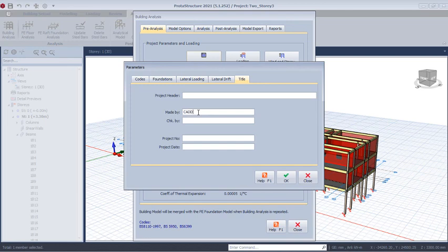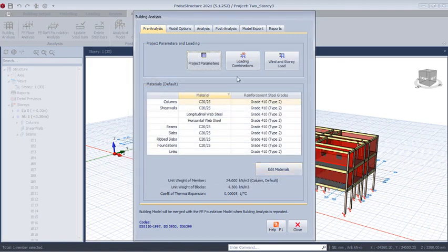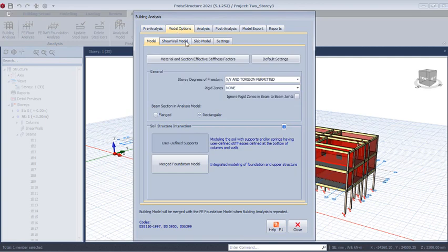Then you fill all of these provisions. For here, the title of the project, you also fill it in. It's very important when it comes to creating a calculation sheet. But all of this can be edited later if you did not add them. Click on the OK option. The most important area there is the soil bearing capacity that we have changed successfully. After which you come to where we have the model options. In these provisions, we don't have anything to change, just leave it at default.